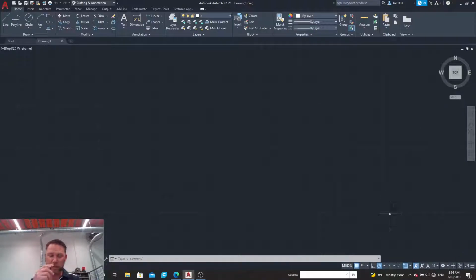Once we've done our setup, we have some basic steps that we follow in order to draw this as a 3D model. First, we draw it from a bird's eye view in 2D. Once we've done that, we join and region. And essentially, a region is turning some lines or some arcs, like a closed polygon, into a sheet of paper. Once we have turned it into a sheet of paper, we extrude it.